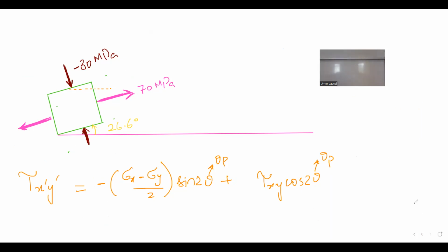For the principal planes, you will not have any shear stress whatsoever. They will be devoid of any shear stress. So actually, when I am making this particular plane, there is a maximum normal stress, just maximum normal stress. And now if I have to design this structure, for example, I'm putting a load of, I don't know, 5 kilonewton.